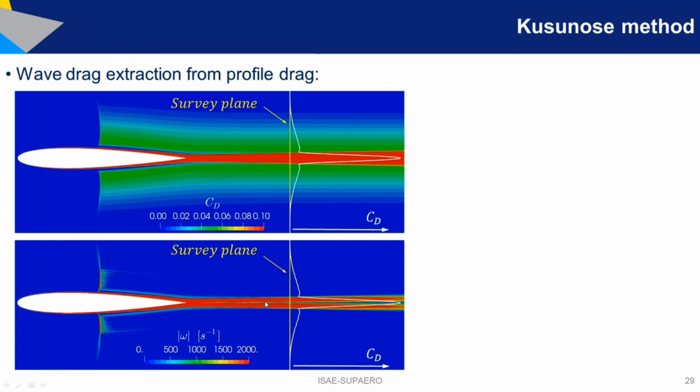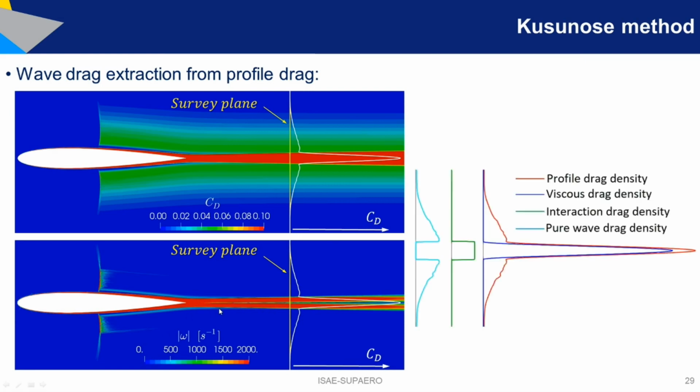He realized that the vorticity is only limited to the wake. So he realized that he can use this parameter to clip away this distribution in white, that is this one, depending on the part of the distribution that lies inside or outside the wake. So basically this is just a wake detection parameter. So the idea is the following.